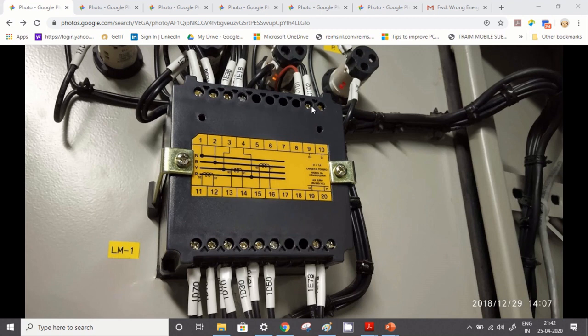On the next day in the Vega meter it is showing 68.2, but on the remote monitoring you will see only 68.0. It stays that way till it becomes 68.9, and when it becomes 69, then only you will get the reading 69. After that again it becomes 69.1, 69.2, 69.4, 5, 6, 7, 8, 9, and then it becomes 70. So when it crosses 69, you will get the reading. When it crosses 70, you will also get the reading. In between you will not get the reading.